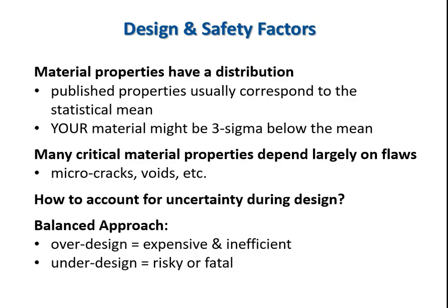inspection method is perfect. The other thing that's not shown on this slide is how your customer might use your material. Just because somebody says they're going to take it to a certain temperature doesn't mean they won't inadvertently overcook it. Maybe people don't know exactly what their loading is. Maybe there'll be a loading factor that no one had counted on. Sometimes even a big safety factor won't account for that, but it at least accounts for a certain amount of human uncertainty in a design.